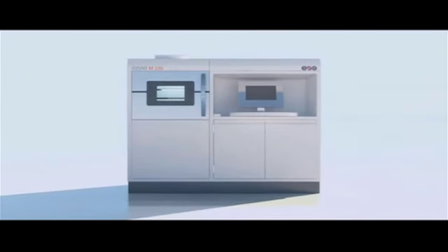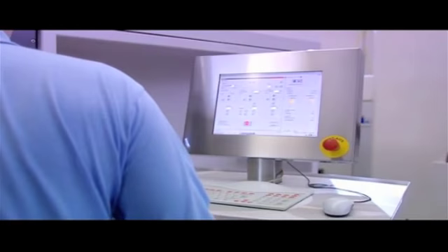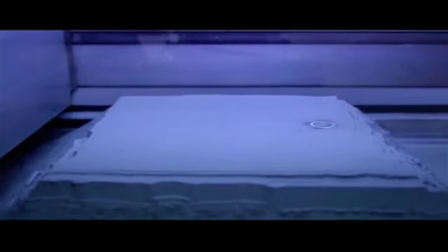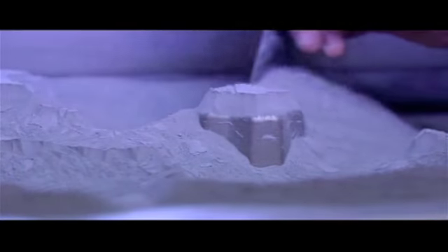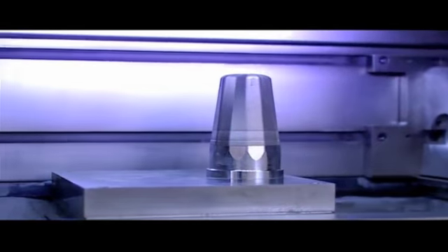This can be in various materials, and materials are increasing every single day. We have a range of metals. We have aluminiums and titaniums and stainless steels and more fancy things like Inconels and Hastelloy X, to a range of polymers and even ceramics. So what happens is, as this part builds up, it fuses to the layer below, and once the part's finished, all you need to then do is simply pull away the excess powder from the part, revealing the solid part finally on the build platform.